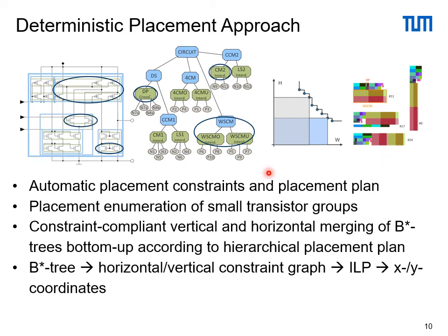The interesting thing is the whole thing takes a few seconds, maybe a minute, which means the user can look at the placements. And usually what the user does is he or she looks at the placement and sees, those 2 transistors, they don't really are where I want them. And then they find out, oh, we need another constraint. You add the constraint, restart, takes another few seconds or a minute, and you can look again and proceed to what you want here.